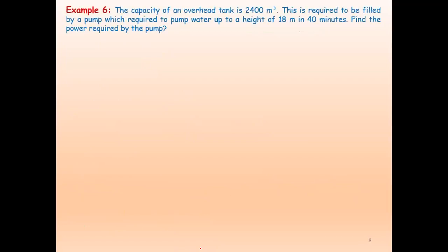So we have the next problem, which is based on again a pump. The capacity of an overhead tank is 2400 meter cube. Now it is the capacity given in only meter cube. This is required to be filled by a pump which is required to pump water up to a height of 18 meters. So head is given, in 40 minutes. So time is also given. Find out power requirement.